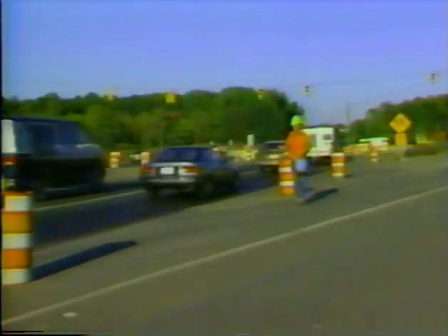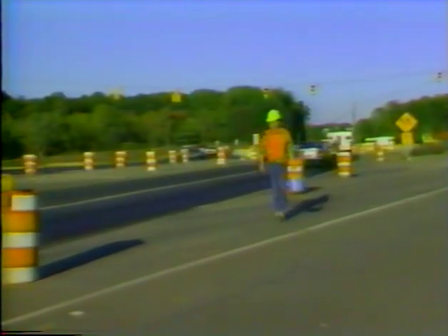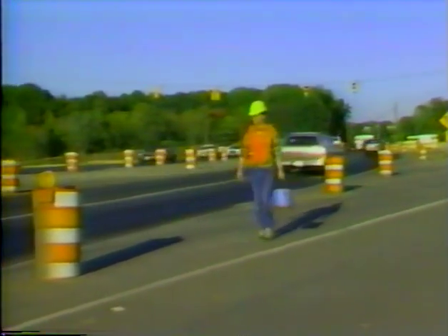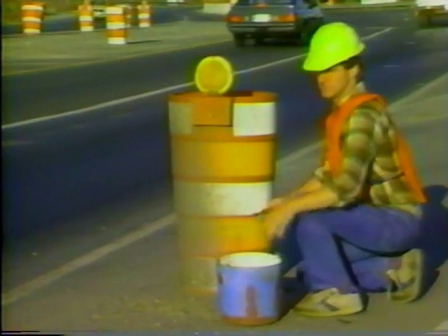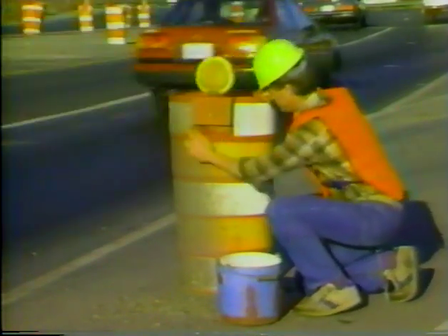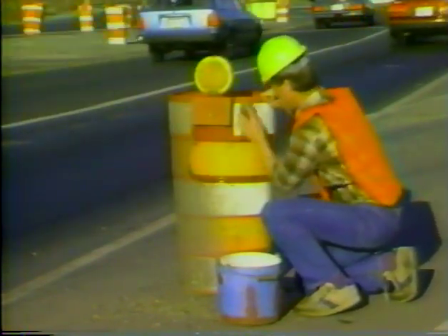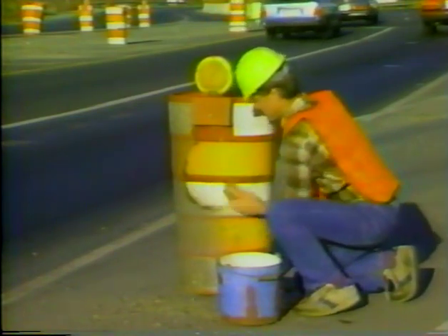Routine cleaning and replacement of signs and channelizing devices should be encouraged, if not required outright by the plans. Construction dust alone can diminish brightness by 50%. Worn out or damaged sheeting will reduce it even more.